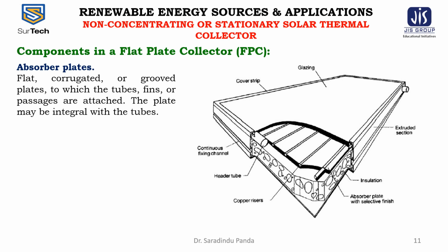For the fluid heating collectors, passages must be integral with or firmly bonded to the absorber plate. A major problem is obtaining a good thermal bond between the tubes and the absorber plates without incurring excessive cost of labor or the materials. The material most frequently used for the collector plates are copper, aluminium, and the stainless steel. The ultraviolet resistant plastic extrusions are used for low temperature applications. If the entire collector area is in contact with the heat transfer fluid, the thermal conductance of the material is not important.